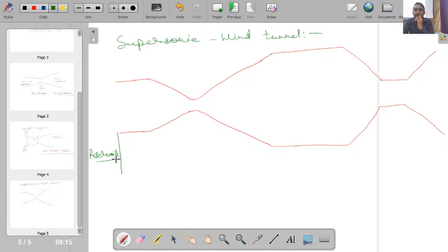Corresponding to this, whatever pressure and temperature I have, I can call these the stagnation pressure and stagnation temperature, P naught and T naught, and so my Mach number will also be very low. Now if I use some mechanism to pull the air into this section, I will have a Mach number less than 1.